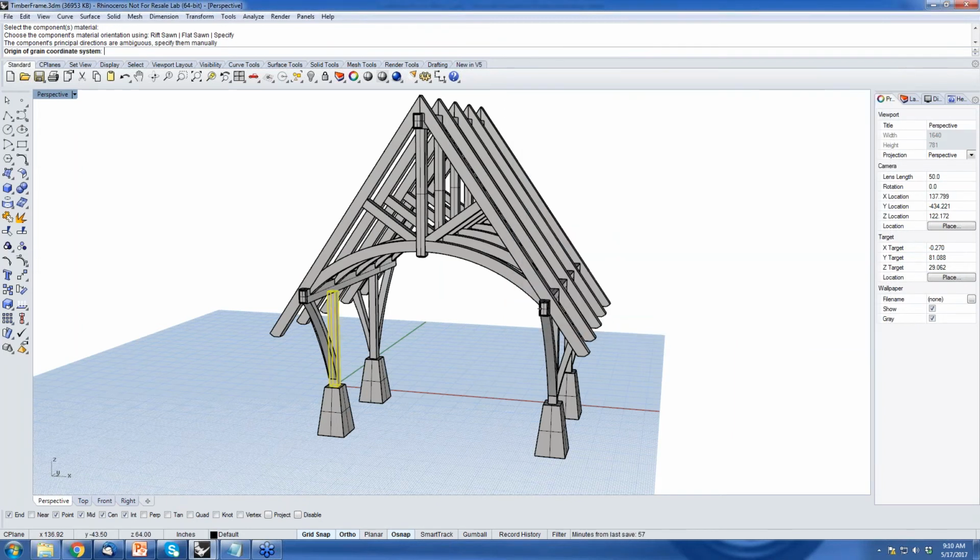And what Scan&Solve Pro will do is identify the principal moments of these geometries and apply the wood grain in such a way that the long direction is aligned with the long dimension of the geometry. In some cases, the shape is ambiguous about which orientation is which.